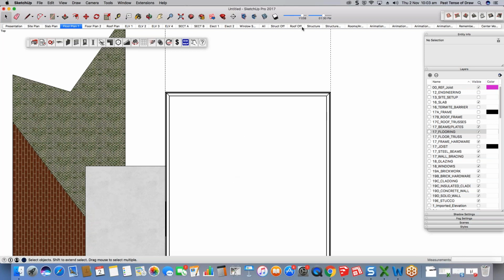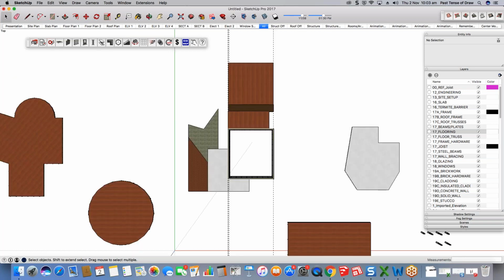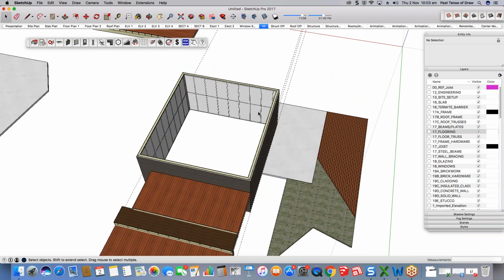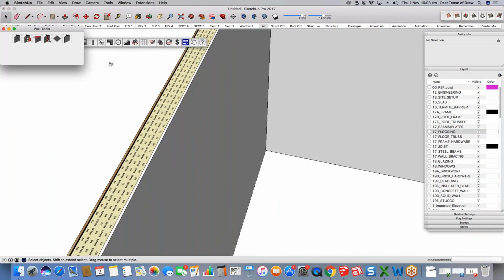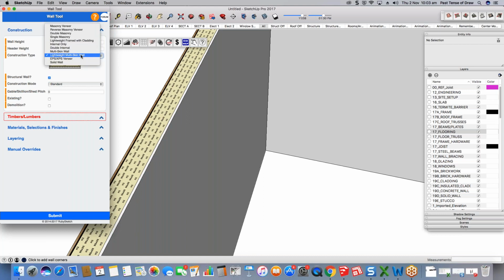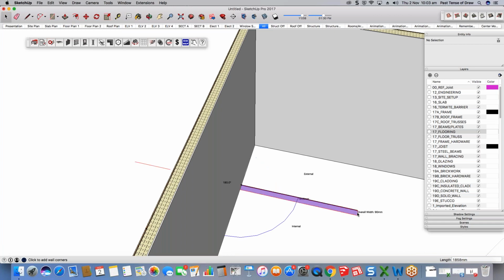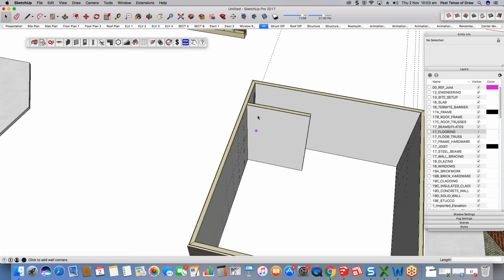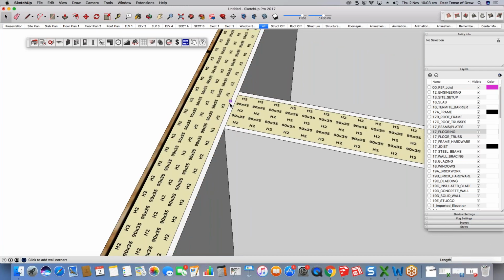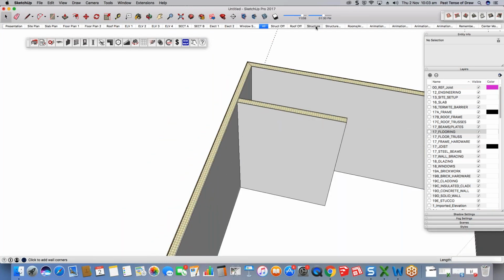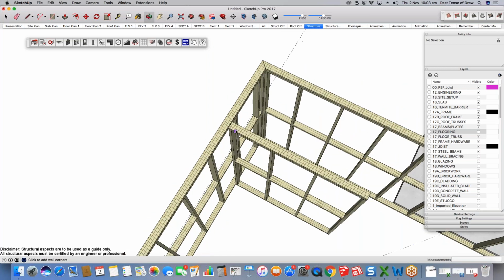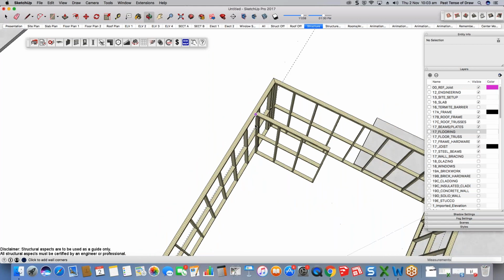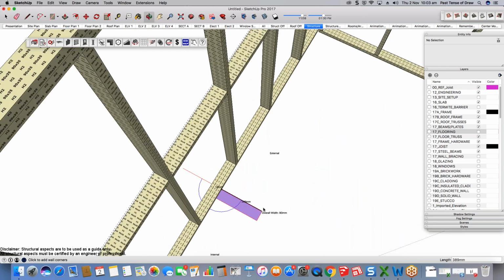But if you're in 3D, the problem is if you're in the all scene, you've got your internal finish. This is a problem that a lot of people make, because when they go into the wall, for example, they start to model, but they're not really aligning structure. I might have this one, press submit, and if I grab it from there and start to draw, you'll see in a second that it's aligning to the actual internal lining. To make it easier for myself, I just turn it into structure mode, and therefore I'm not going to have this gap. When I grab my point in my structure, I'm going to get it from the actual right point so that my structure is aligned.